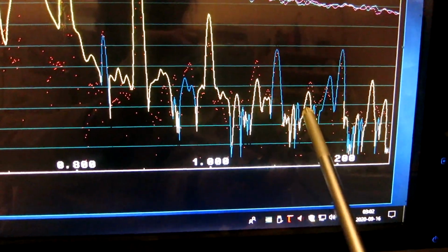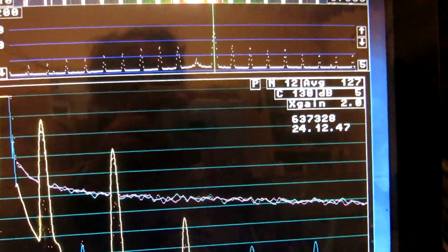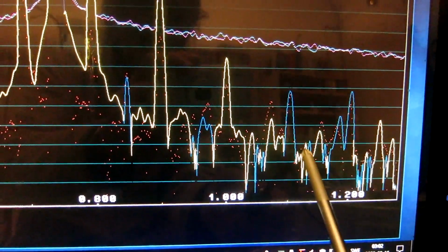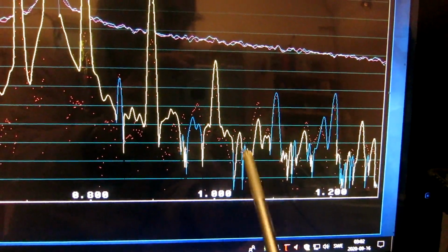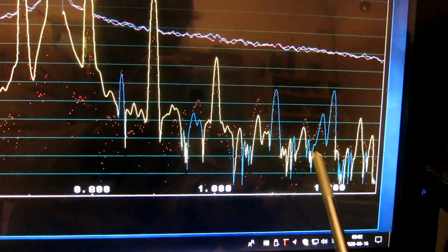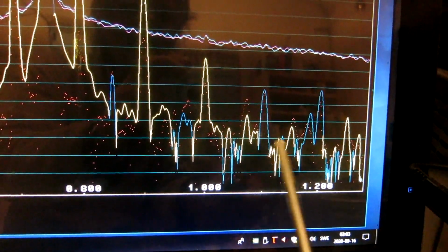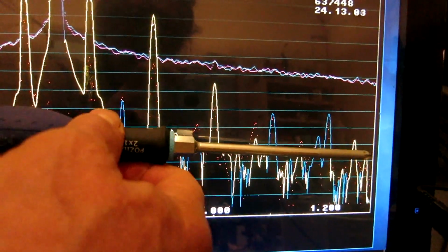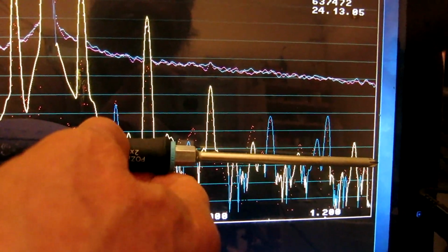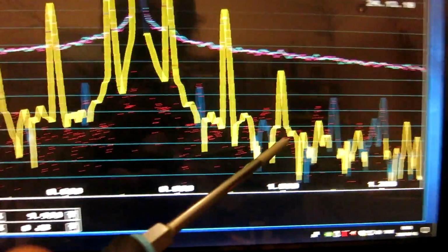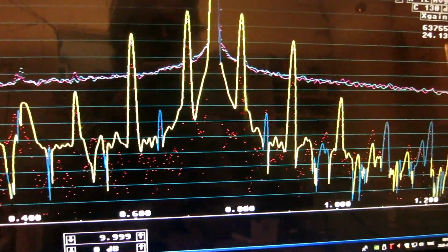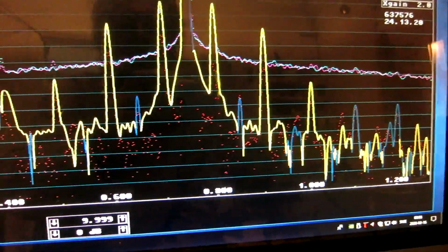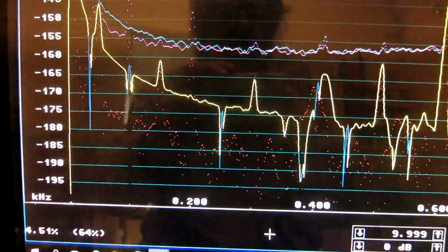But here the time, I have been waiting 24 hours, and I would have to wait about 8 times longer or more to see this properly. But I think I can conclude that this level I see here, as I hold the tool, something like this, and this line is minus 185. So, conclusion, my system is not good enough to study the sideband noise above about 300 Hertz.